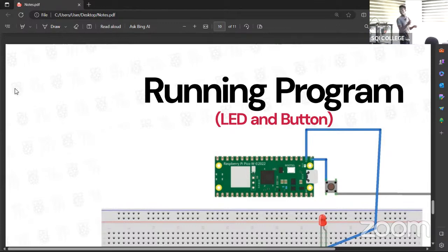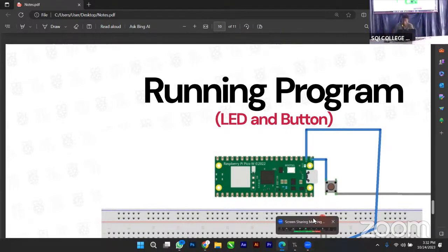There's something called floating state, meaning that if you don't declare your pin, every pin that is not being used is floating between 0 and 1. Now, if you don't declare that when I don't push this button it should be automatically high, it is just going to fluctuate between 0 and 1. Do we get it? That will bring us to something called pull-up.